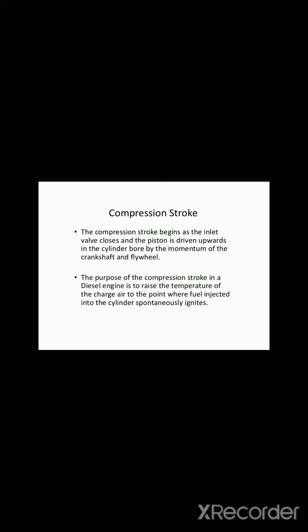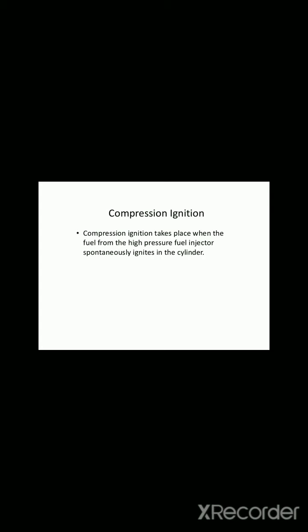The purpose of the compression stroke in a diesel engine is to raise the temperature of the charged air to the point where fuel injected into the cylinder spontaneously ignites. Next is compression ignition. Compression ignition takes place where the fuel from the high pressure fuel injector spontaneously ignites in the cylinder.